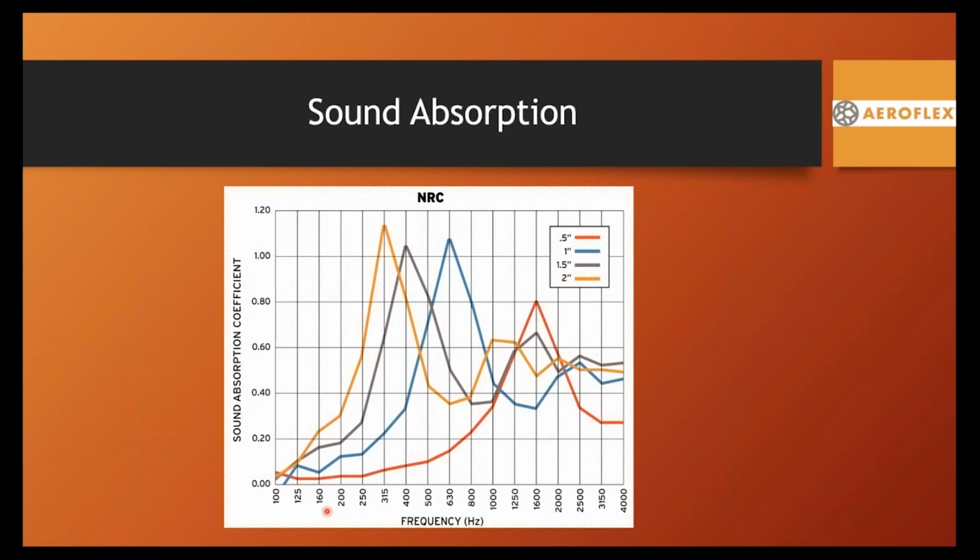So it can attenuate fan noise, airflow, and sheet metal vibration. And it may be a cost-efficient alternative to expensive silencers and things like that acoustic consultants have to also consider. Open cell liners like fiberglass do a very good job at the upper frequencies, say from 500 to well over 1,000 hertz. So that's where it's determined by the acoustic consultant if it's going to be elastomeric or fiberglass.